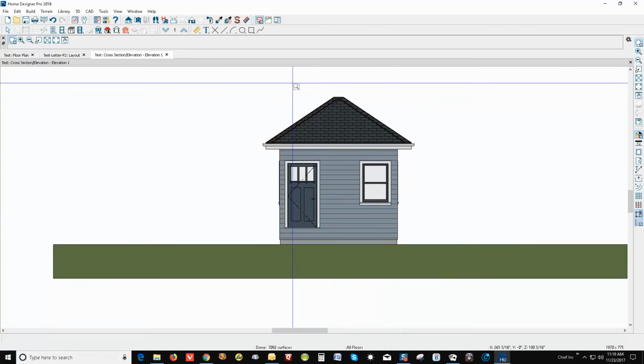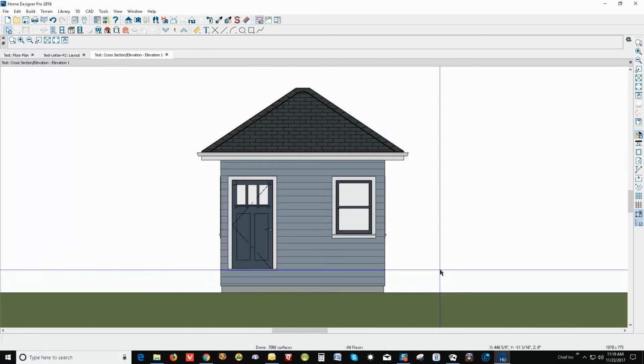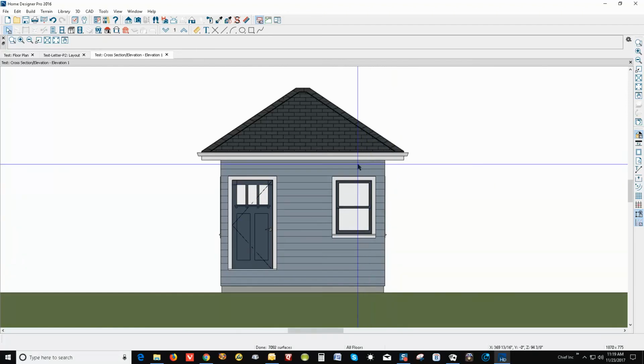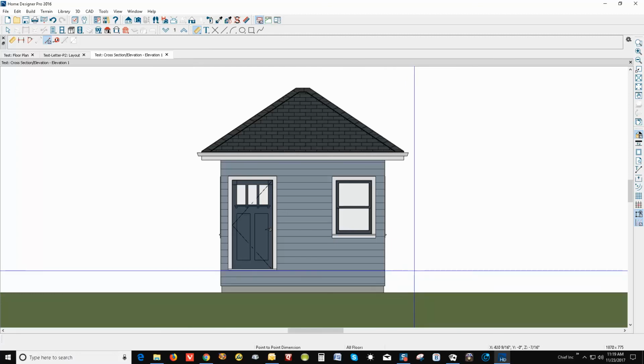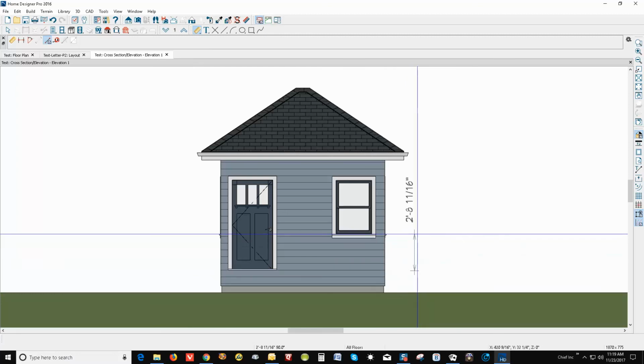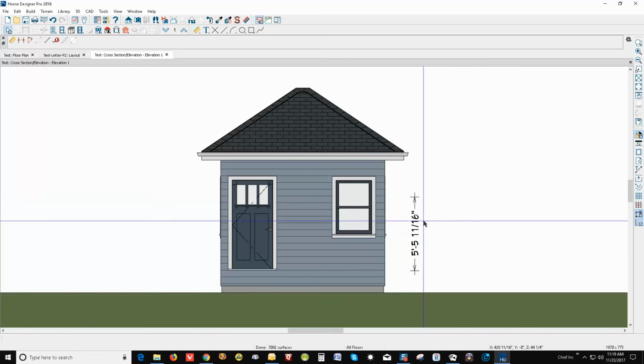I'm going to zoom in here, and if I want to add dimensions, well, I'll add dimensions. We'll click on the dimension tools. I use this point-to-point dimension tool because it doesn't readily measure to 3D surfaces, but it creates its own points here.